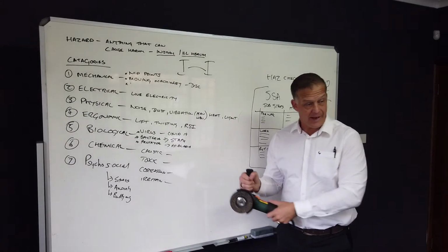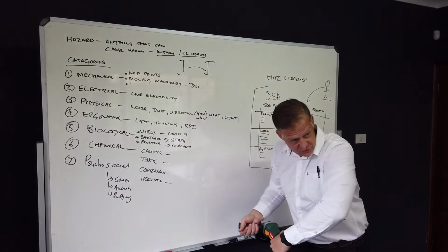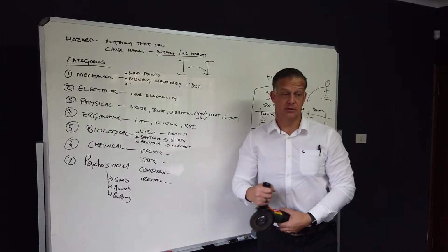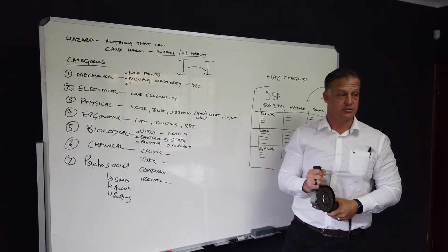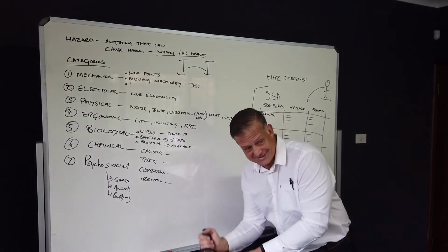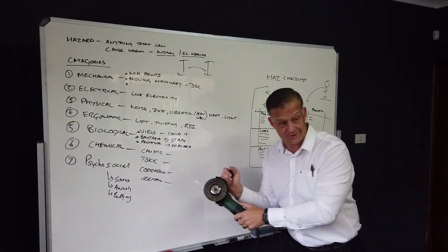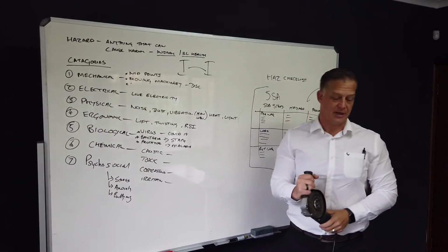Activate the machine and grind. Do you think I should grind cutting towards myself? No, definitely not. That can result and has resulted in some very, very nasty injuries. So when I'm grinding, I'm cutting away from myself, making sure that I'm not cutting towards anybody else.